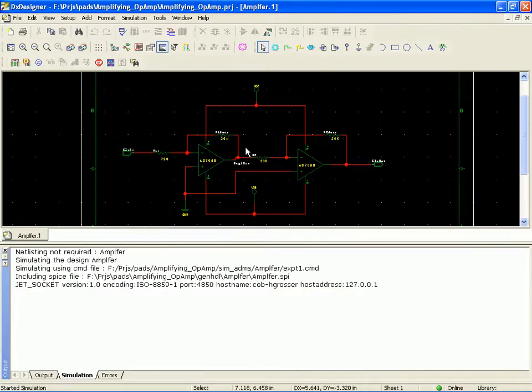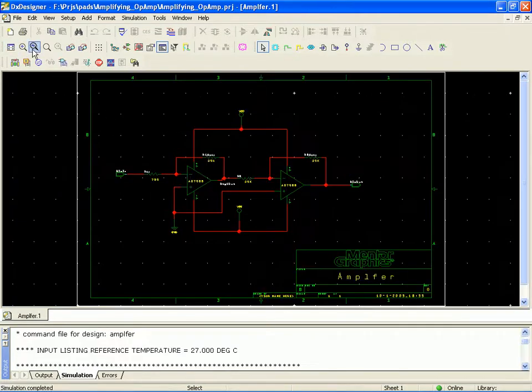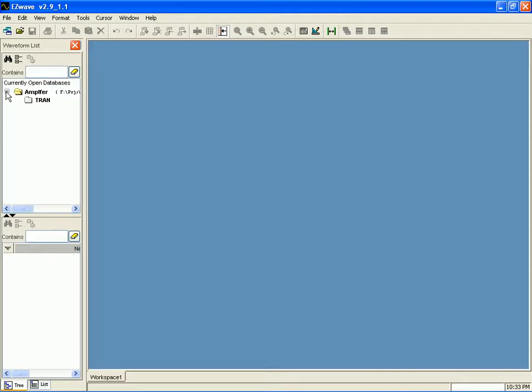TX Designer is still active when the simulation is running. So if you want to pan and zoom or work on your schematic while the simulator is running, you can continue to do that. So you can see that it's completely functional. And here comes EasyWave for HyperLynx popping right out. So now you can see that in this case we've just passed the specific signals that we said we were interested in over to EasyWave for HyperLynx.